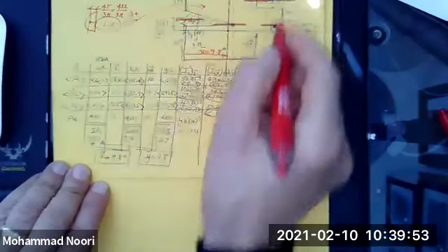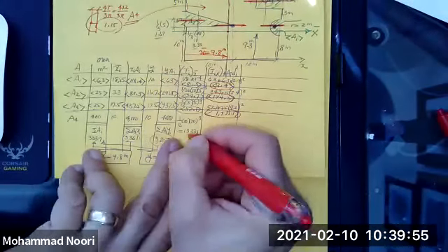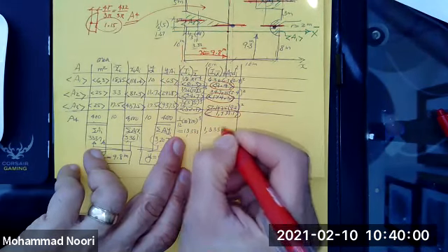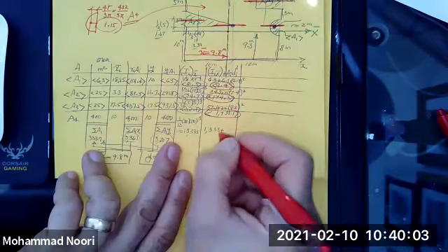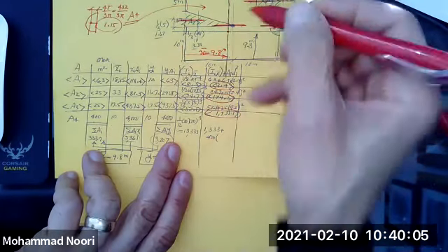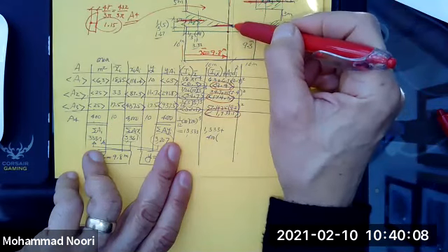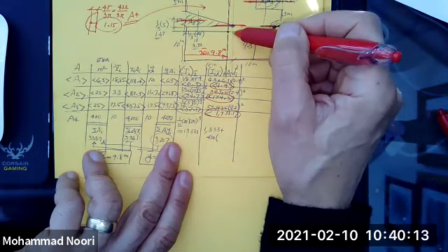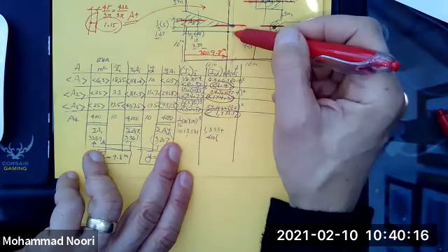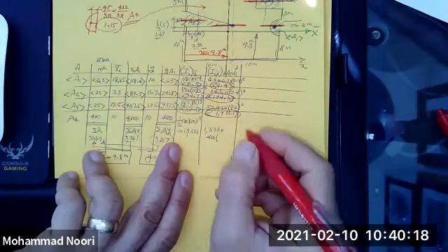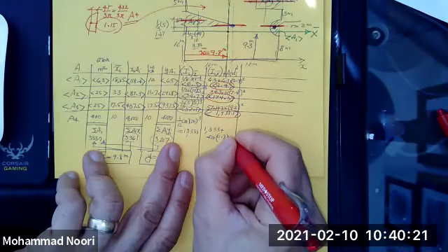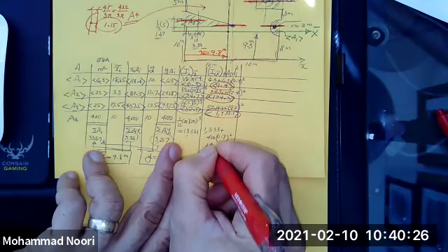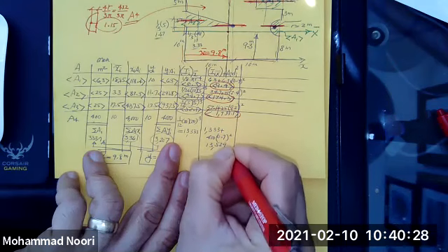How about for this one, A4? Again, you have what you have here, 1,333 plus its area, which is 400, times the distance from the centroid here to here. This is 10 minus 9.3, 0.7 squared. Calculate that, it gives you 13,529.